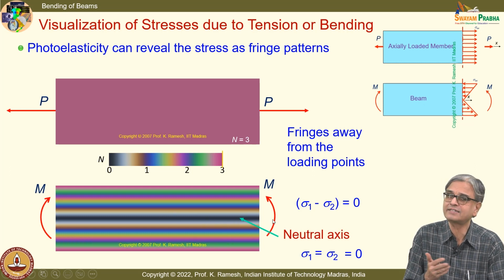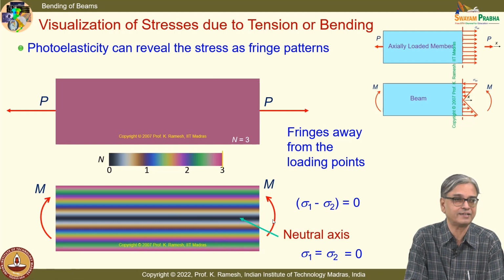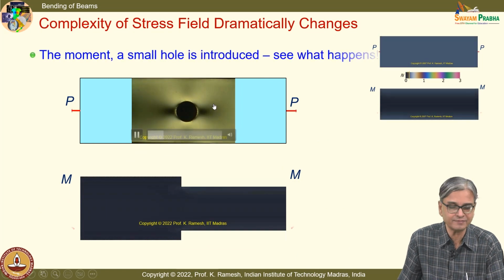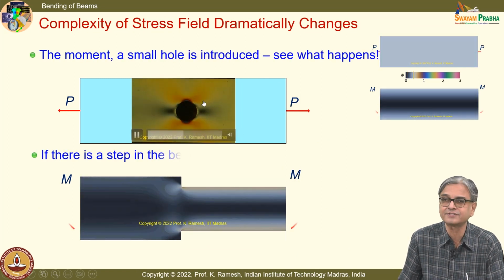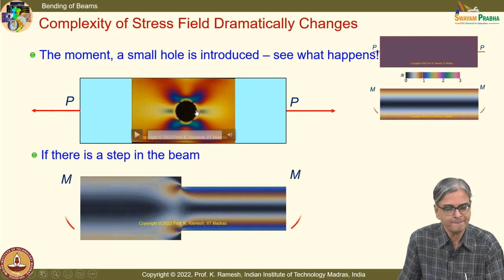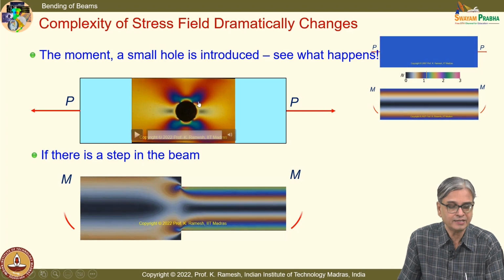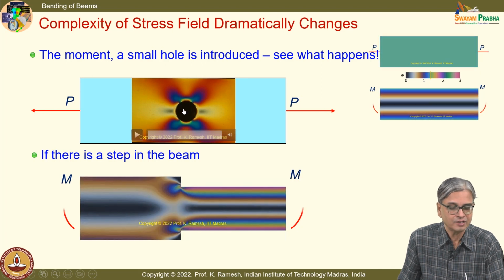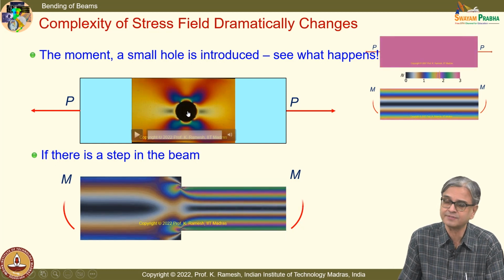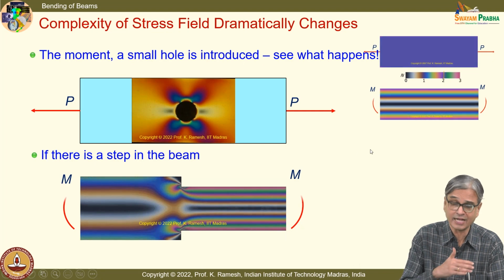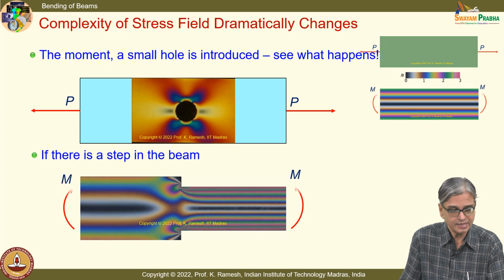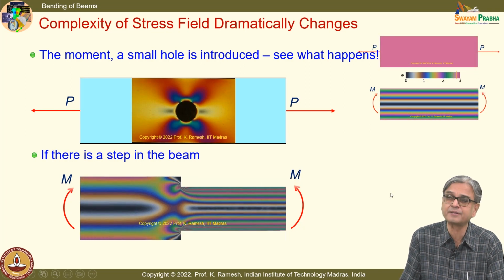And we have also looked at certain modifications in our earlier development. I put a hole in the tension plate, you have a beautiful play of colors, and we also said that this is stress concentration, and the stresses go to a finite value. When I have an infinite plate with a very small hole, it goes to 3 times, but for a finite plate it goes higher than that, which you can determine only from an experiment or from a numerical study. And we have also looked at a stepped beam.